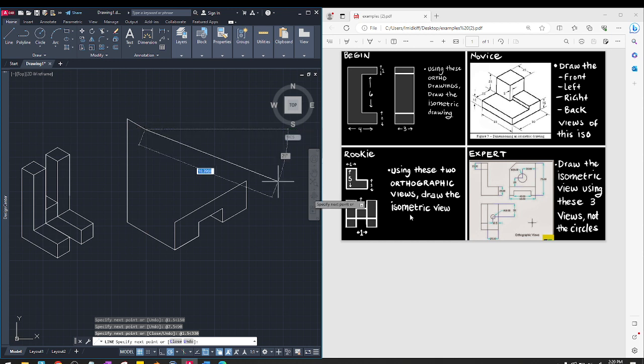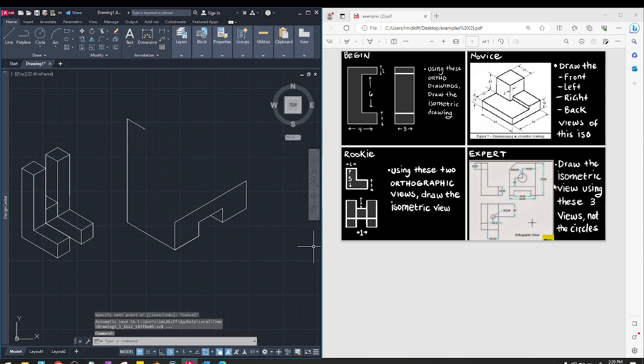So now the overall height of this thing is 7.5 minus 2, which is 4.5. So I'm going down 4.5 at 270, which is wrong. I am not doing math in my head. Is that 5.5? Yeah, why would that be 4.5? That's clearly 5.5. Okay, now I'm just going to go down 1. I don't know why I did that. And connect it over here at 30 degrees. Okay, so I've made that L right there.